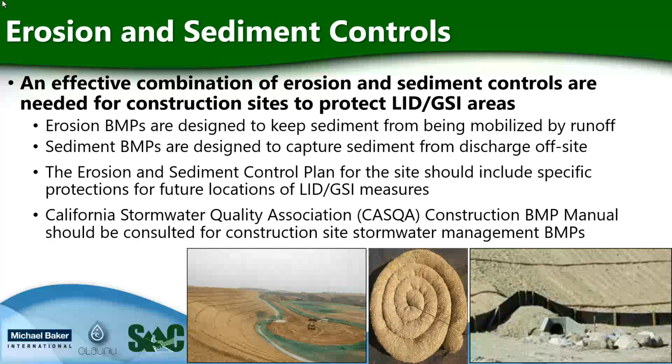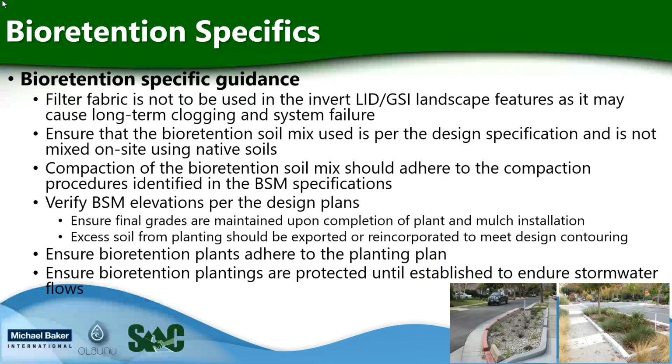We'll now get into a little bit on bioretention specifics for construction. Although used early in the development of bioretention systems, filter fabric should not be used in the invert of LID and GSI landscape features, as it may cause long-term clogging and system failure. Sediment migrates down to this layer and occludes the layer and prevents draining of these systems. Filter fabric should not be used in the invert.